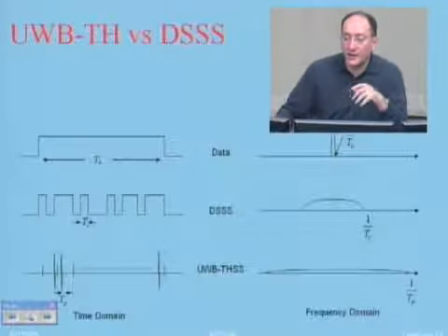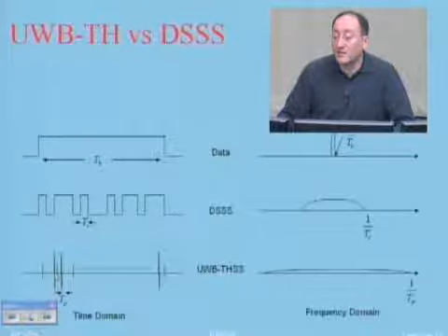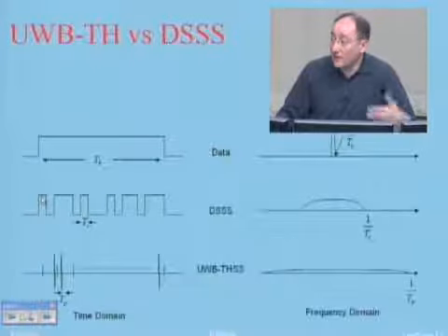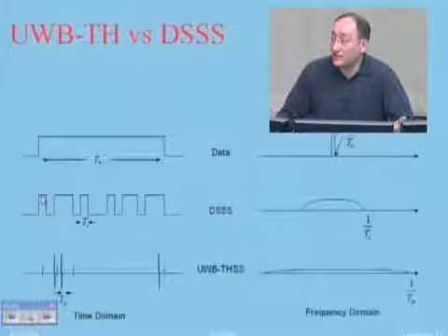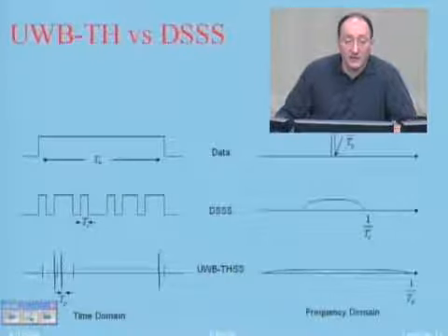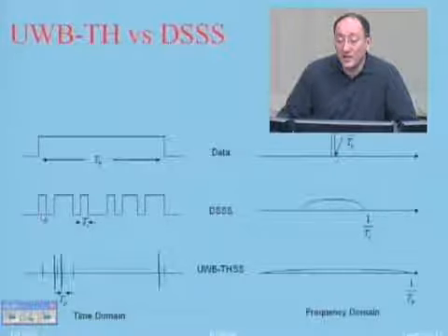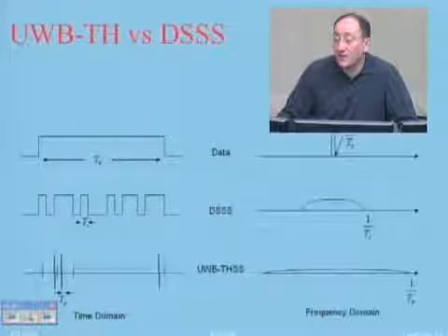Now, in this part, I'm taking advantage that in time domain, I'm sending pulses rather than chips, so I save in the energy. But again, in the world, you never gain without loss. What is the loss? In a spread spectrum, my spectrum is the inverse of this length, which is something like that.